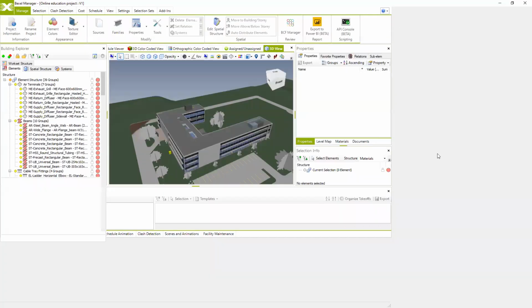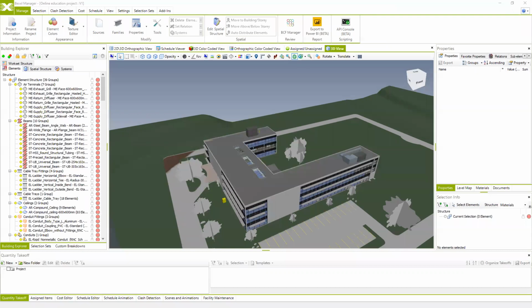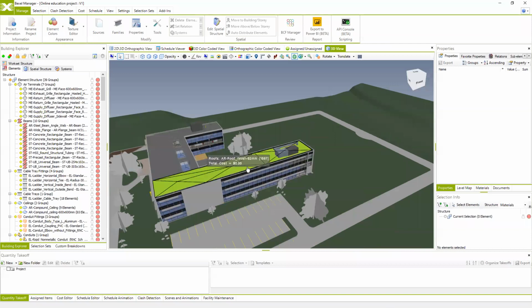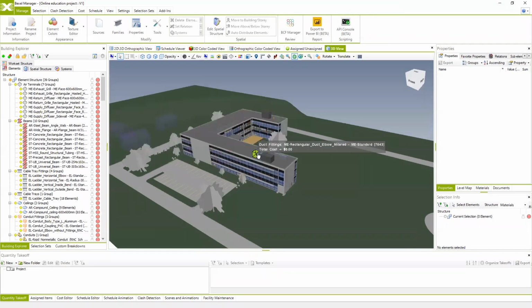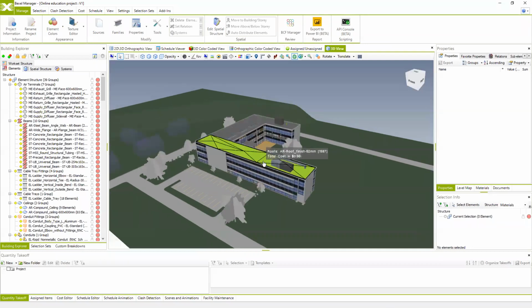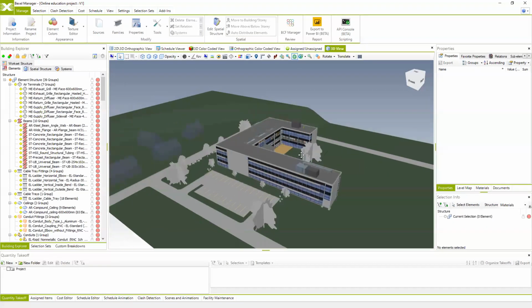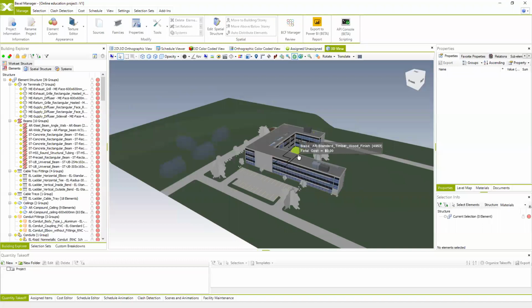And now let's go back to today's topic, which is grouping and creating basic scenes and animations. So why is grouping important? The groups can be used for linking BIM model elements with the building zones, or creating schedule tasks from them, or for creating different kinds of clash detection jobs, or any kind of additional model segregation which has to be used for multiple purposes.